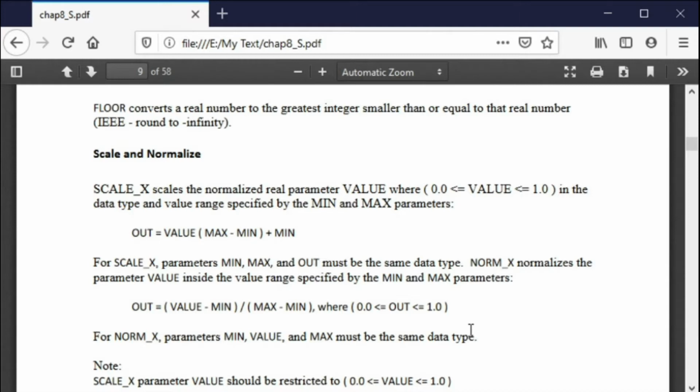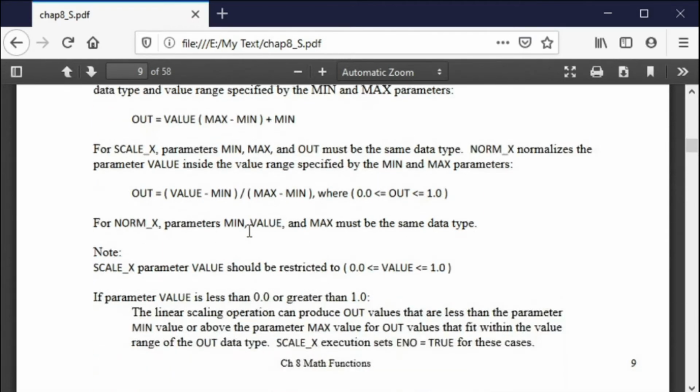So again, this is the Siemens approach. Allen Bradley lets you do the scaling as you configure the card for the inputs. In other words, they do it separately. They do it as you're configuring the card. Siemens does it inside the program itself.